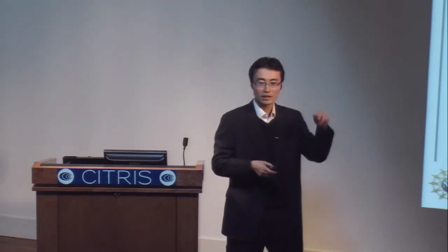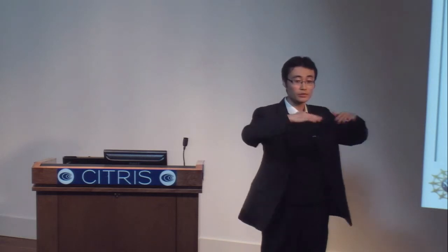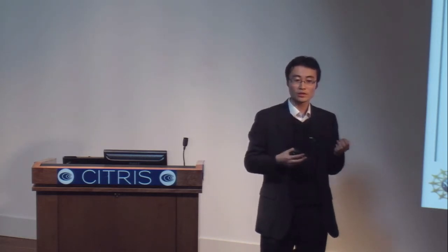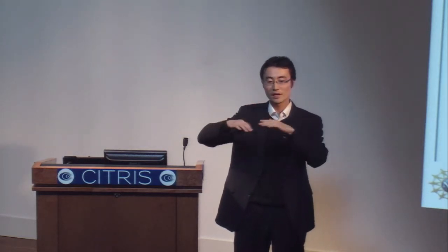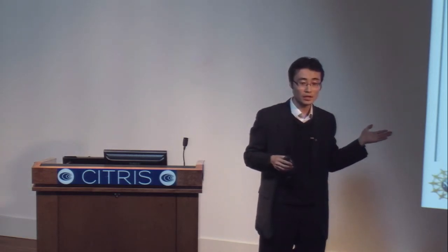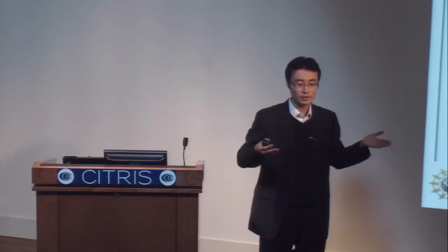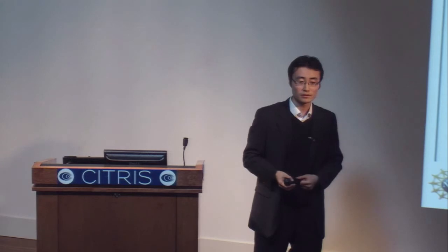What that shows is the actual adhesive energy of these graphene is actually much smaller because the restorative forces should be much smaller in carbon nanotubes and graphene. So if you use the mechanical robustness of a traditional MEMS structure and have the contact made with these graphene, which I don't think anybody has ever done, we may actually reduce the hysteresis by a great amount. And that can be very helpful in reducing the overall scale of these nanoscale devices.